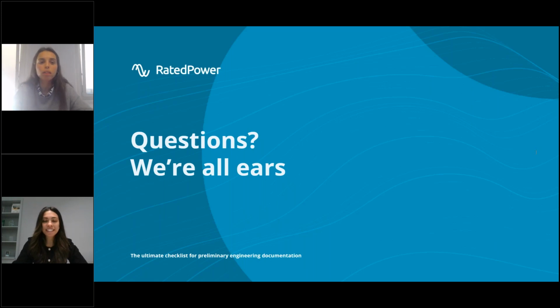The first one is to you, Irene. Am I right that PV Design works on a flat terrain only? So all data, for example in the DXF file, will be valid only for flat terrain? Okay, so no, PV Design also works with more uneven terrains or high terrains. You can work with any topography, because in PV Design you can upload your own topography data, and you can make the topography analysis directly in the software.